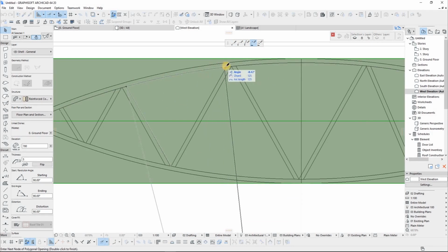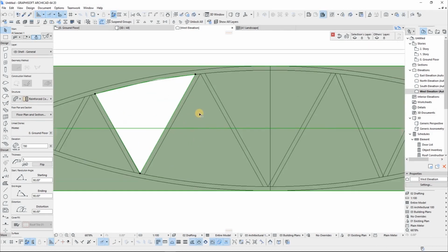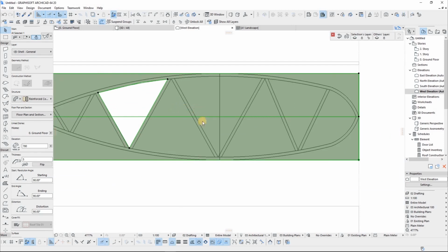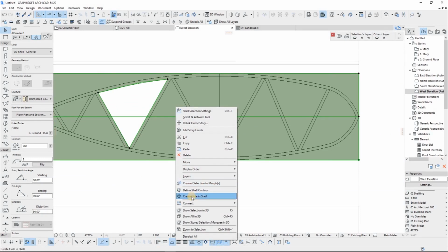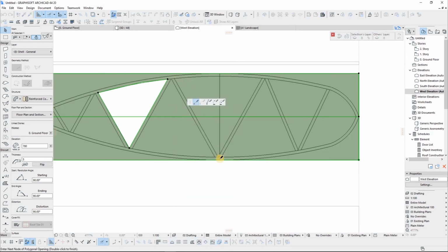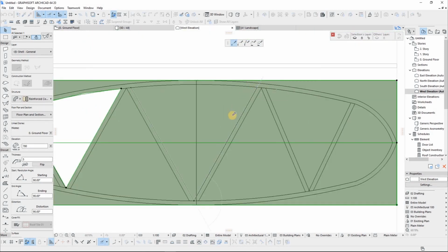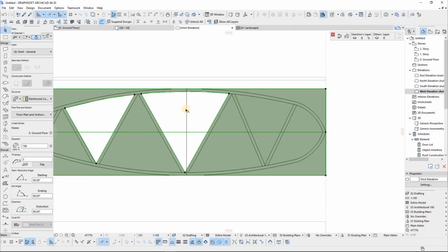This is what I want to do. Also, from that point I just want a straight line. It doesn't have to be perfect right now, and I'm going to do another one just so that you guys get the gist of it. Create another hole from that point to there, and then do the arc by 3 points as I did on the previous hole that I created. Combine that and then it creates another hole.